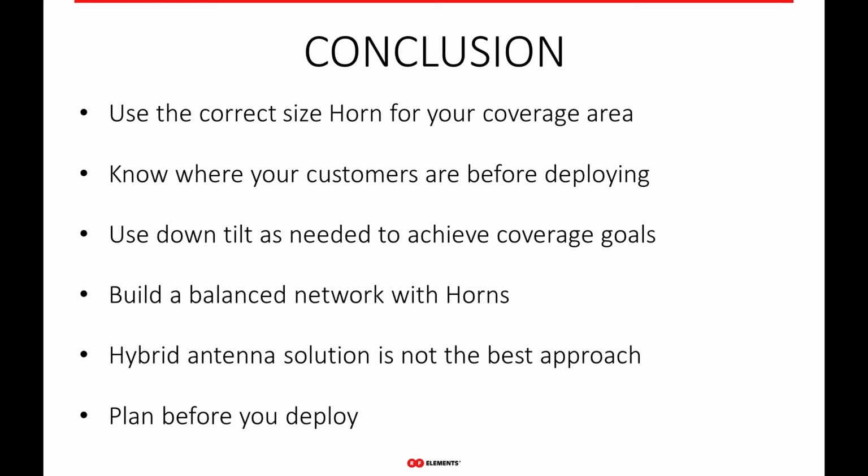Build a balanced network with horns. Again, this all comes back to using the proper antenna based on distance, based on coverage area. If you build a balanced network, where the diversity of connected clients and their data rates are more uniform, you'll have a much better running network.